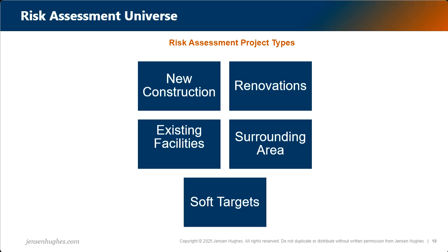So the idea of an add, remove, and change, really we're looking at the scalability of that camera head-end structure or access control. How many more devices can we add? Are there any caps to additional? But then of course we look deeper into conduit pathways and your head-end space. Is there truly room in those areas to expand? And in most cases, they are not. So we have to consider potential migration to a new head-end location or additional conduit infrastructures.